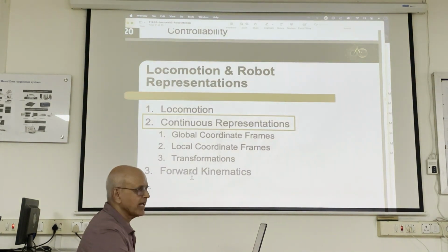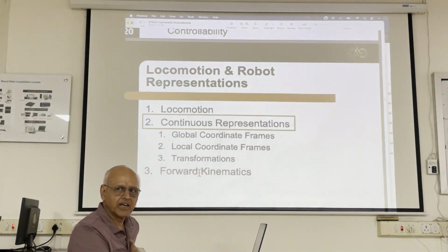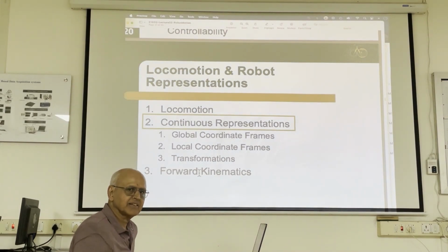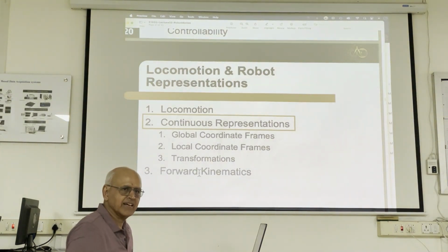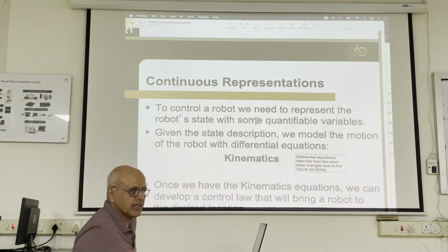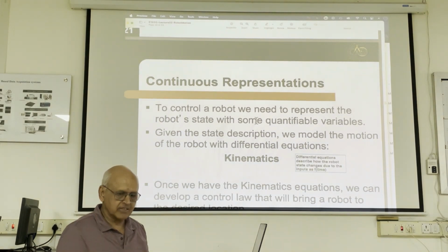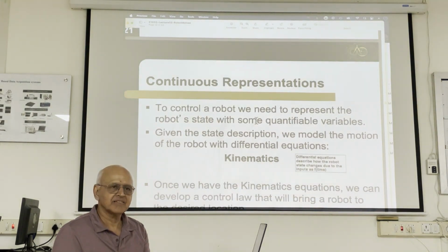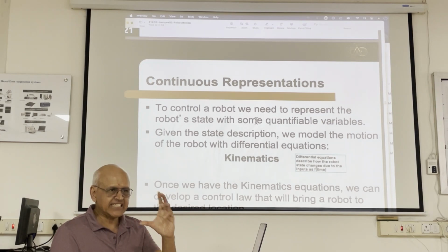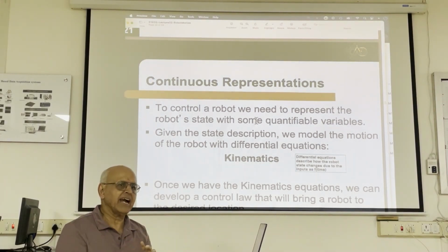And then we're going to obtain the equations for a differentially steered robot in the kinematic mode. We're not doing dynamics anymore because it's beyond the scope of this class. I told you there's a PhD student of mine working on that separately, trying to model a robot's dynamics. So whenever we want to control the robot, right, we need to define what are the variables we're interested in controlling. So for instance, it could be x, y, theta. So then we create a state vector with those three stacked in there.